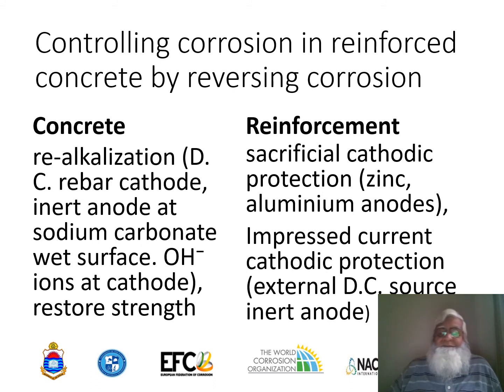the reinforcement, like the steel bars, which are made the cathode, connected to the negative terminal of the battery, and the positive terminal of the battery goes to the anode.